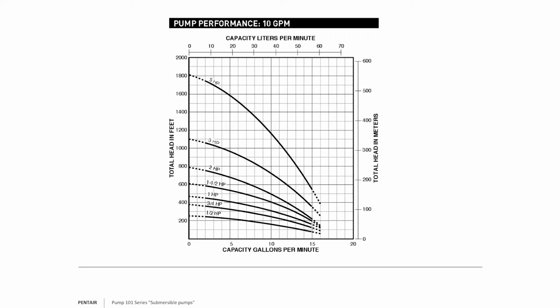In this case, this pump is a 10 gallon per minute pump. In this case, 10 gallons per minute happens to be dead center. But never assume that. Because, for example, a 70 gallon per minute pump might have a maximum range of 0 to 100 gallons per minute. Guess what? 70 is going to be skewed to the right. So don't assume that. Always, if you're looking at, say, a 70 gallon per minute pump, assume that the 70 gallon per minute pumping mark is your best efficiency point, if they don't have the efficiency point properly marked on the chart.